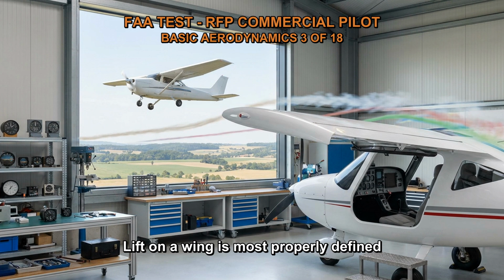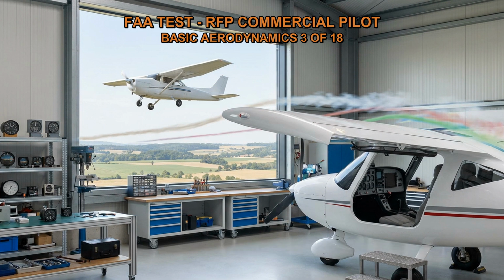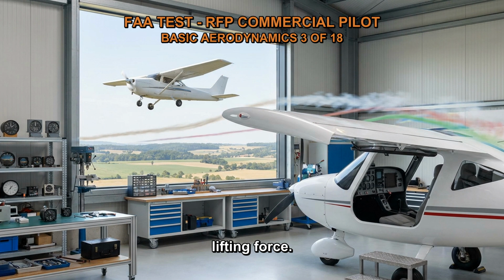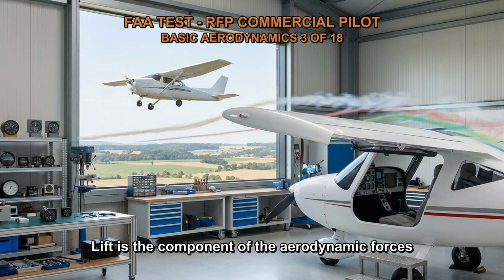Lift on a wing is most properly defined as the force acting perpendicular to the relative wind. When an airplane is in flight, the wing shape and angle of attack create a pressure difference between the upper and lower surfaces of the wing. This pressure difference, combined with the dynamic properties of the airflow around the wing, generates a lifting force. The relative wind is the airflow that the wing experiences as it moves through the air. Lift is the component of the aerodynamic forces that acts perpendicular to this relative wind.